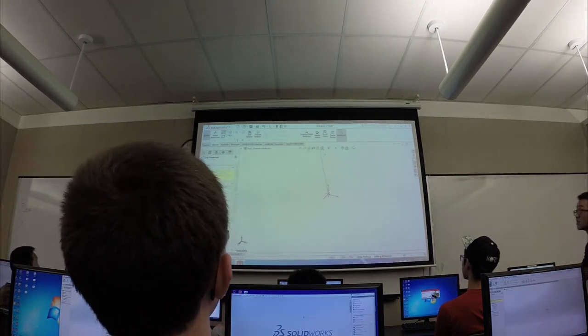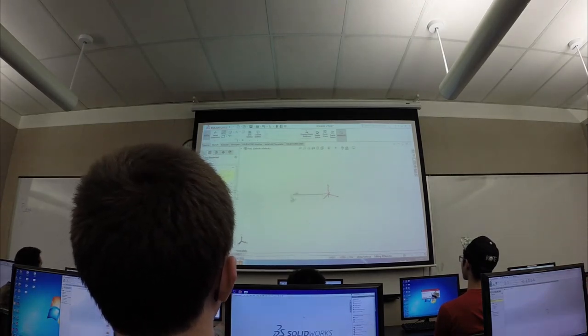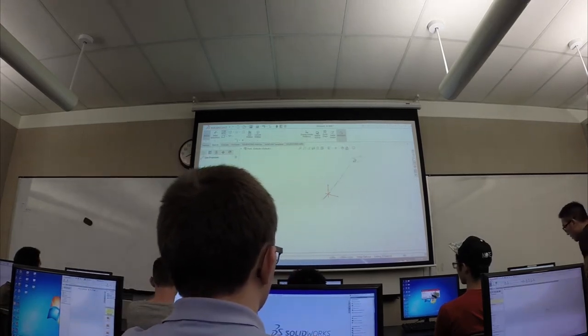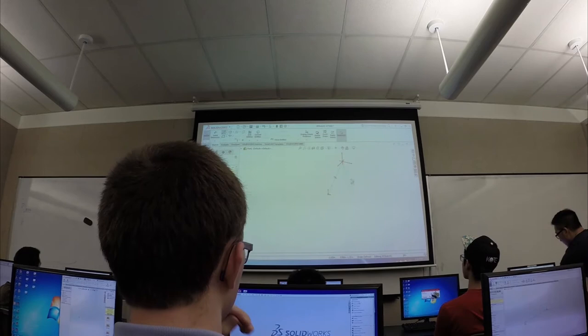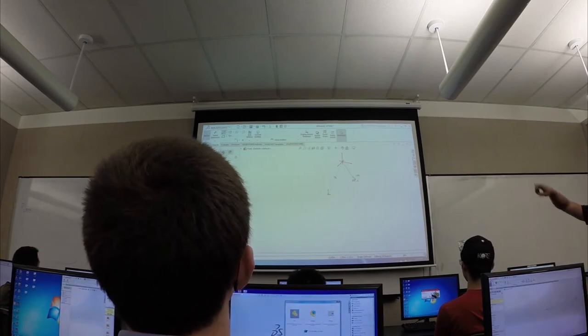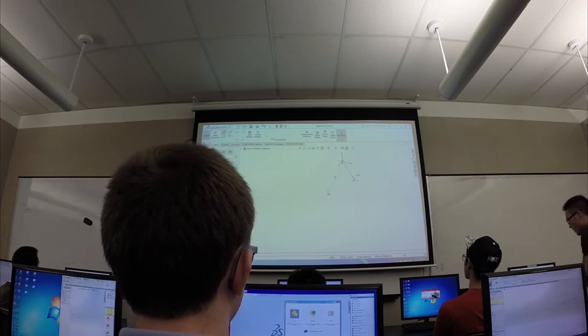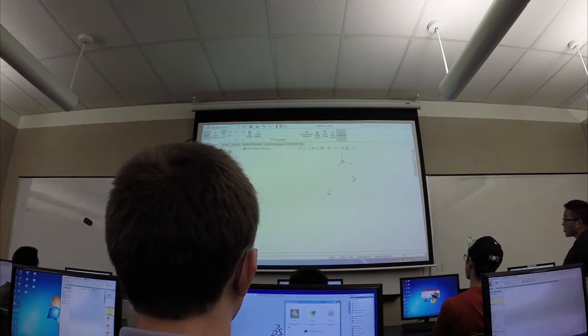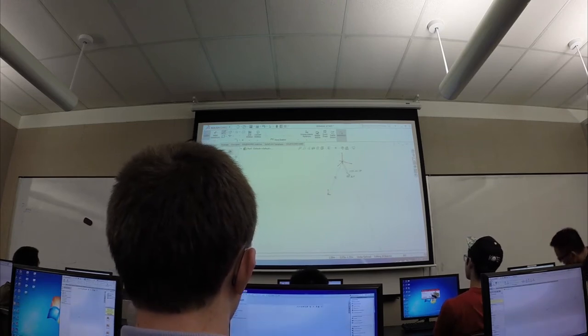So as you can see, I just started drawing a line, right? Right now this line will remain on that XY plane, and then we'll just click anywhere, and then another coordinate system opens up there, right? It's showing you, okay, where are you gonna go from here now? If you click A, you can start switching your coordinate systems.